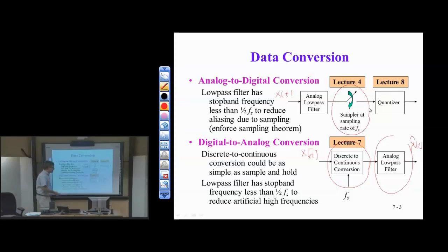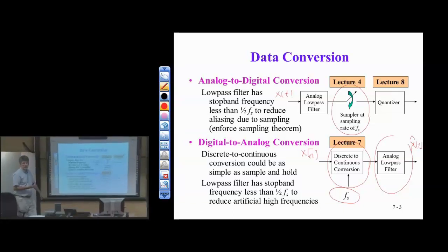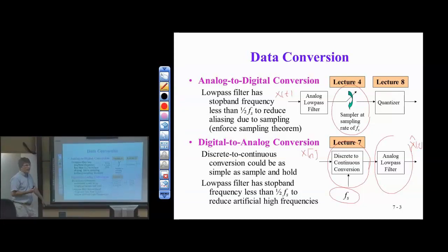Now in discrete time, we've abstracted away the sampling rate that we would have used originally, but that's often kept in the designer's head in the program. So we have some flexibility in how to choose the sampling rate, Fs here. But whatever sampling rate we choose for Fs in the discrete time to continuous time conversion step, it means that we really can only guarantee reconstruction up to half the sampling rate. Any frequency content above half the sampling rate are artifacts, again, from this conversion step from discrete time to continuous time. So again, that's a review from part 1.